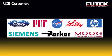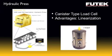There's quite a few applications that we have worked on, but we'll cover a few just to give you guys some ideas. Here's an application where we are bringing multiple load cells into a central location. Using multiple load cells in parallel can be a cost-effective method to measure high loads. You also have the added benefit of measuring the load distribution.